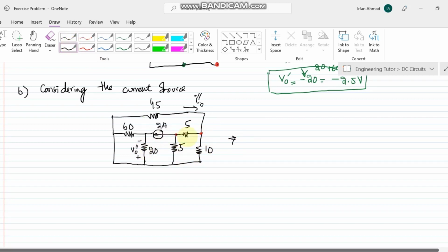Before using the conventional methods of solving this circuit, we can apply the node analysis or the loop analysis here, but we can already see that in applying the node voltage method, we have to identify the number of nodes, and the number of nodes here are 5, in which when one is considered as a reference node, we have to make 4 equations. Solving the 4 equations will be very hard. Similarly, in identifying the meshes or loops here, we have a total of 4 meshes, and applying the currents there and then solving that circuit will also be very hard for us.